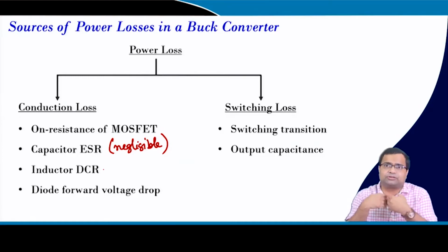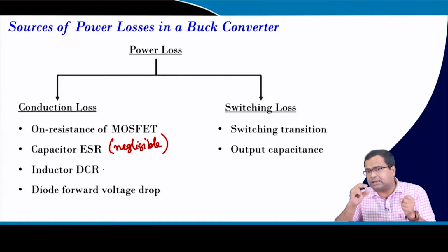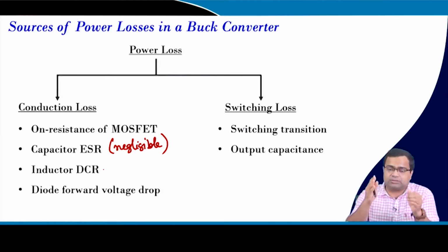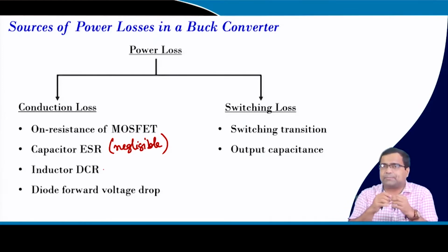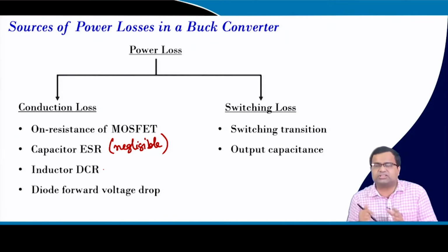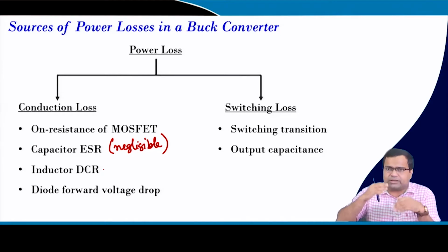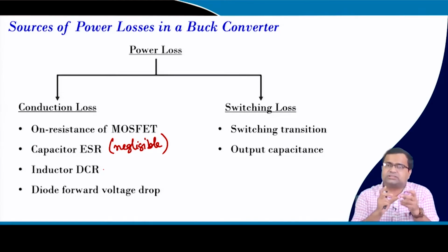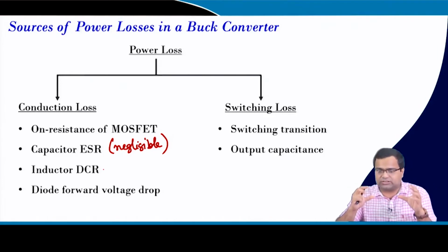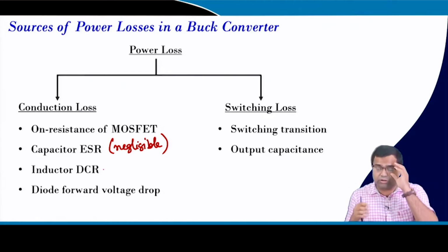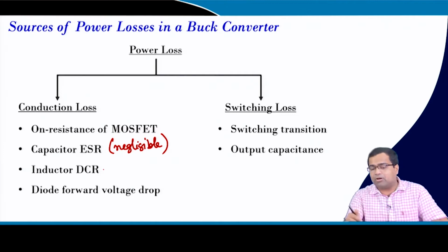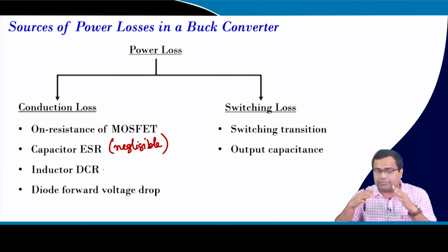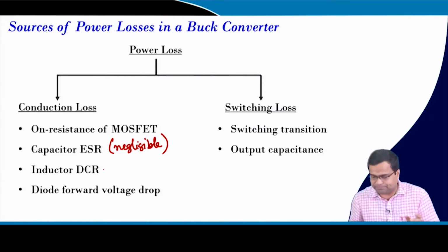And again if you want to turn on, that capacitor has to be discharged, because once it is fully on, the capacitor voltage should be 0 and that energy will be lost. So that is the loss due to the output capacitor. And if you switch more frequently, the energy loss, and hence the power loss due to the capacitance, will be higher for fast switching.